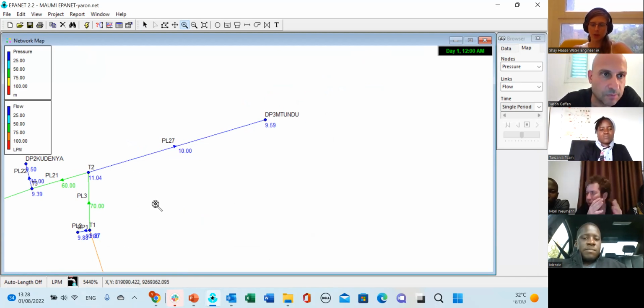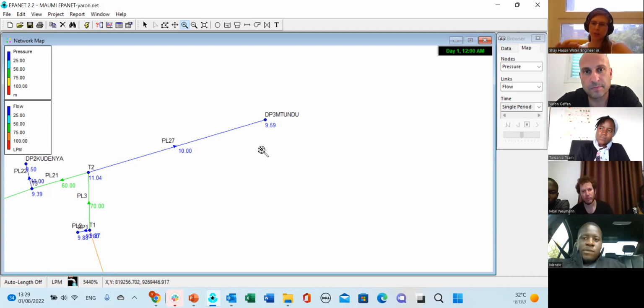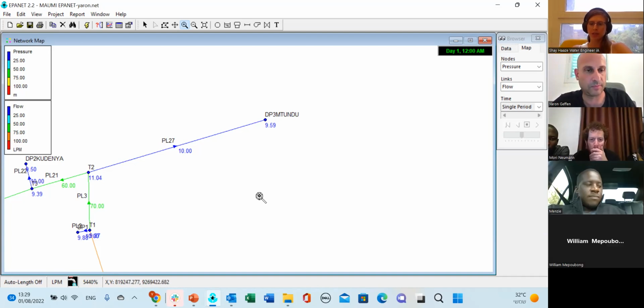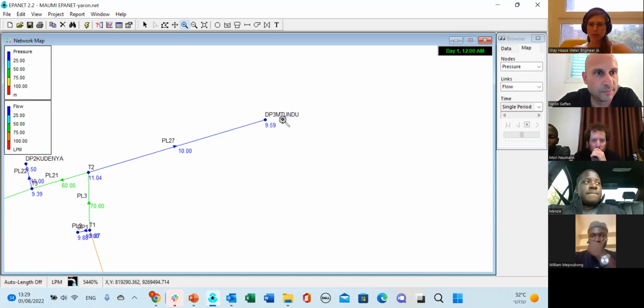I think that's one of the advantages of using the booster pump, that we're not so reliant on the water level in the tank, because the booster pump will give us pressure all the time, straight pressure. And then we can model it to be whatever we want. And with this, changes of 3 meters here or there do not change the pump so much. So we don't need to get a larger pump just to get that extra 3 meters of head. So that's the big advantage that we can have with the pump, besides the fact that we can reach higher elevations. So yeah, I think that's the point, and it's a good question.